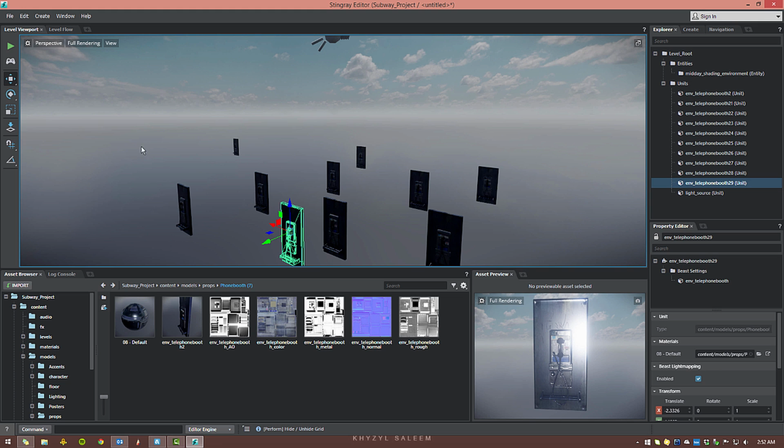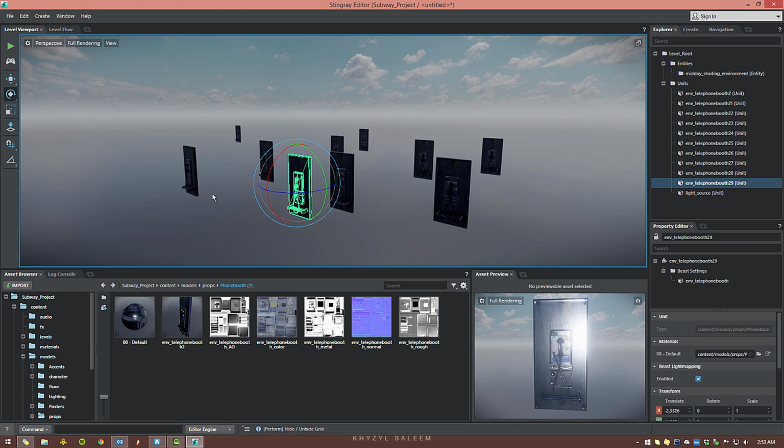All right, I'm going to turn the grid off here. And then below that we have grid step and angle snap, rotation snap, in case we want to rotate. So if I go to rotate, and by the way, your move, rotate, and scale tools are hotkeyed just like Maya. So you've got W, E, R, and so we'll go to rotate with E, and then let's say I turn on the snap, and if I hold it down I can change the snap value. So let's go with 10-degree increments here. So now as I rotate, it should be rotating in 10-degree increments, and if I go back to 45, we can see here we now rotate in 45-degree increments. And let's just go back to 1 degree, but you can also choose custom, obviously. All right, and then the same thing, we have our grid snap.